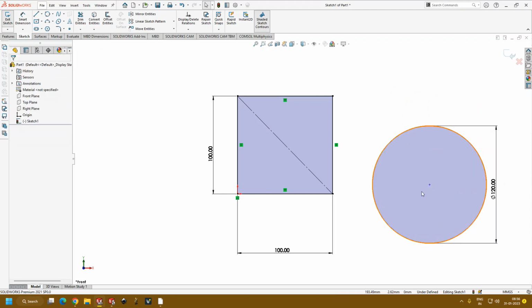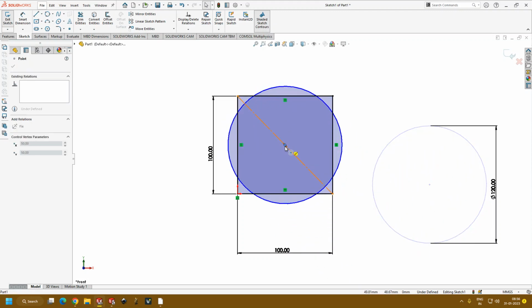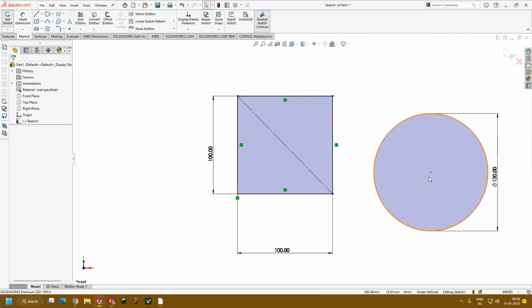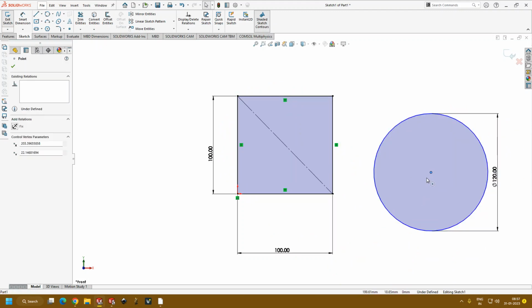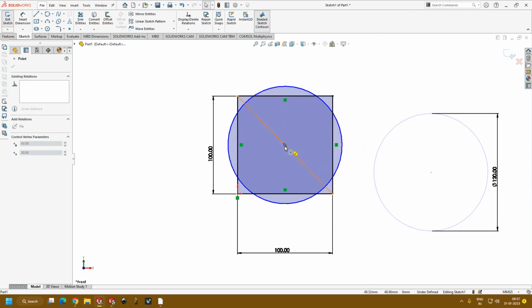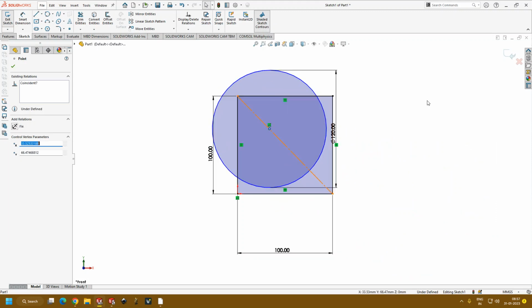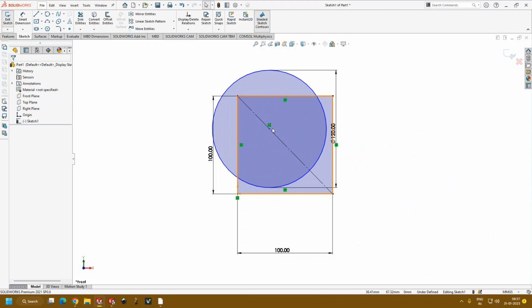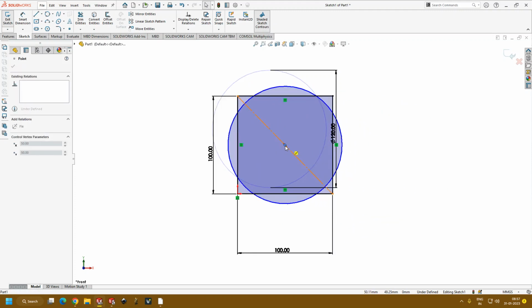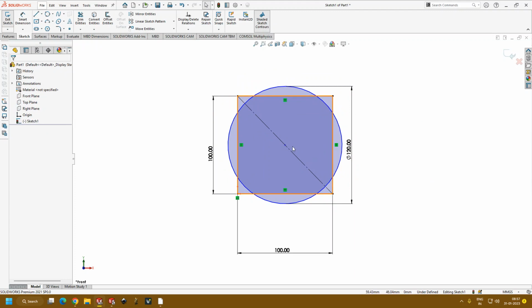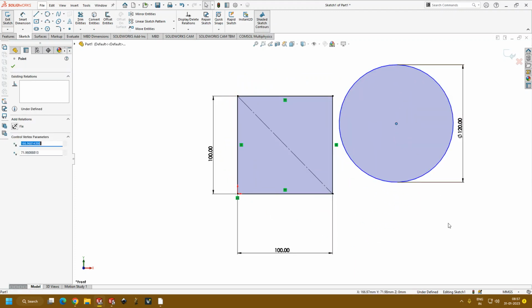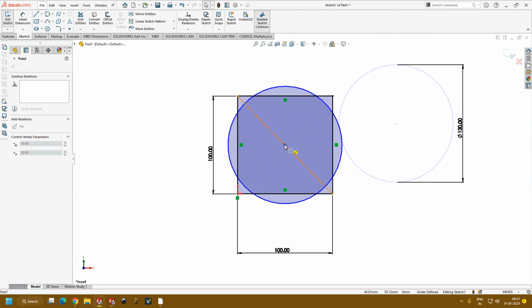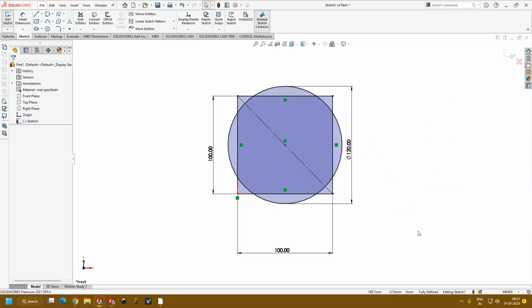there are two options you can do. One is, once you have mastered this, you can just drag and drop at your required point. So simple. Click this point and drag. You can drop at any point. For this line, you can drop at the line also. No problem. Again, you can delete this constraint, and again you can drop at the center. You can again delete this, and again drag it outside. So this is for once you get used to it.